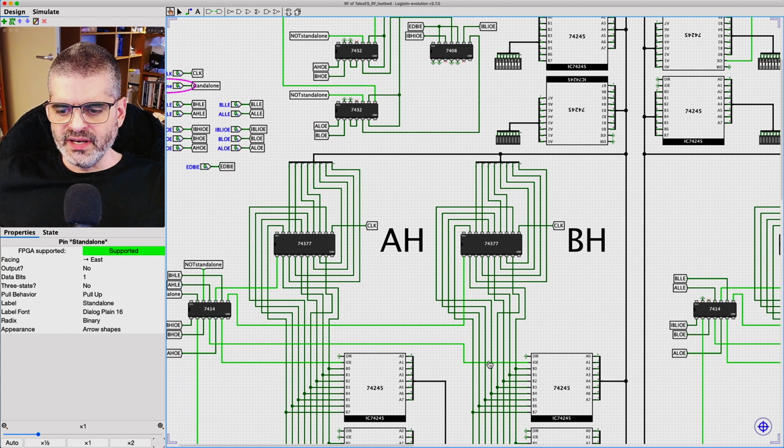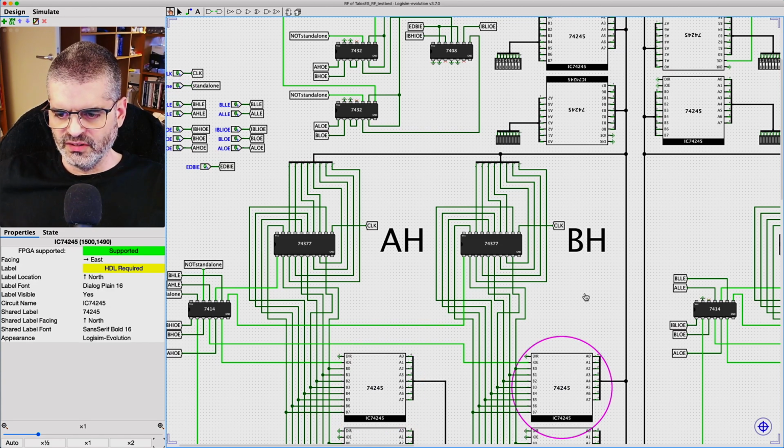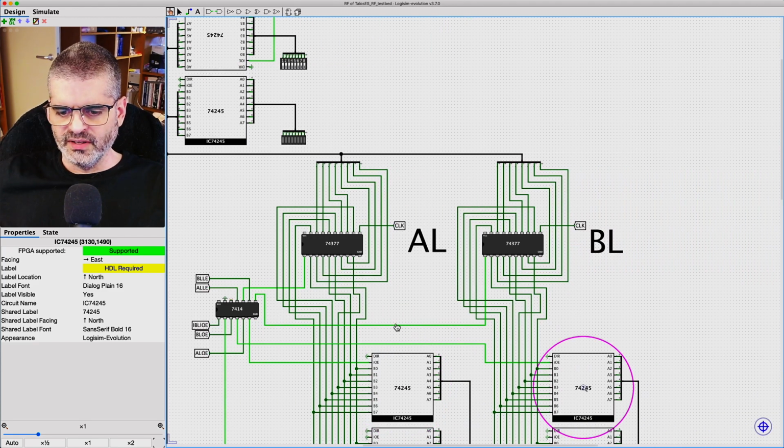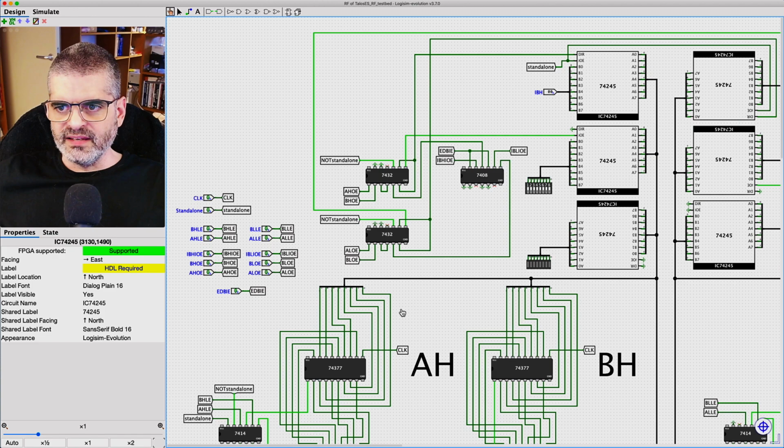So if we enable any one of these buffers here, or this, then the direction bit should change, because now these buffers should take the value of the local bus and drive them out through the backplane connector to communicate it to the other cards via the internal bus. Is that what happens? This is what's done by this little logic here, three TTL chips.